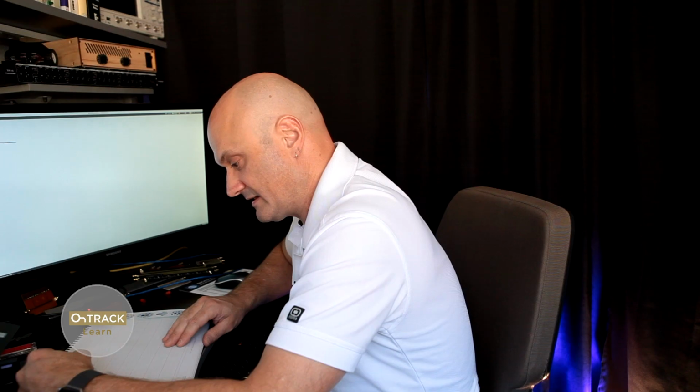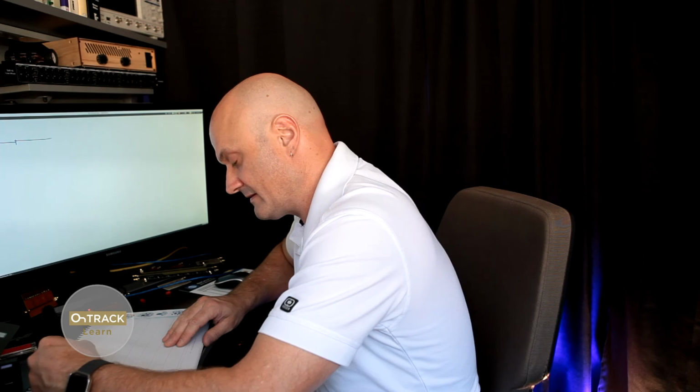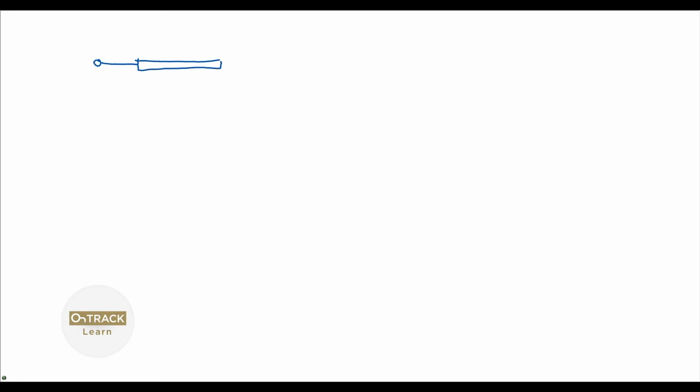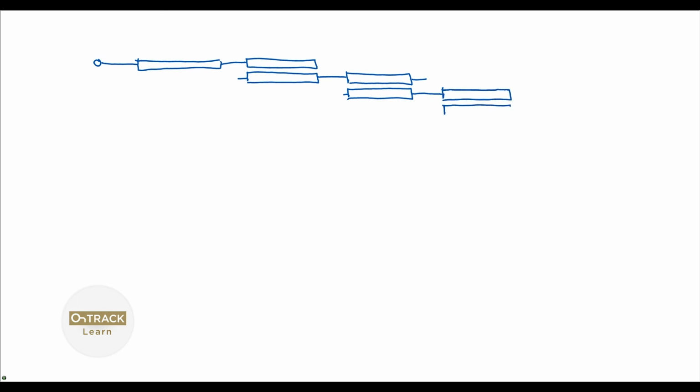So that looks like, here we're coming in, we have an incoming transmission line, then we have a directional coupler, or a coupled line segment, and another coupled line segment, and another coupled line segment, each of those quarter wavelength long, and then our lead out. And this forms a really good bandpass filter.